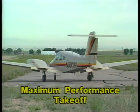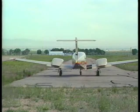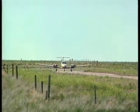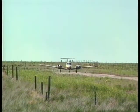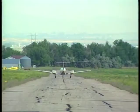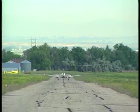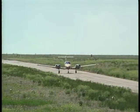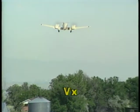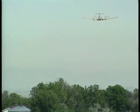If a maximum performance takeoff is required, set the flaps as recommended by the manufacturer and follow the procedures in the pilot's operating handbook. Make sure you use all of the available runway. Apply full power before releasing the brakes. Accelerate to the recommended liftoff speed, or VMC, plus 5 knots, whichever is greater. Rotate firmly and accelerate to the best angle of climb speed, VX. Retract the gear when you have a positive rate of climb and can no longer land on the remaining runway.